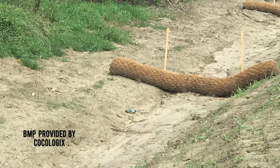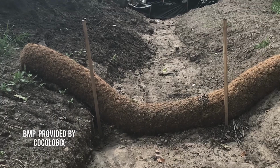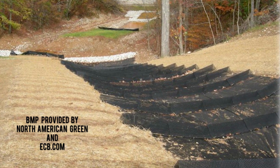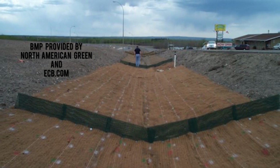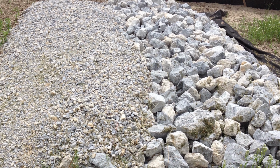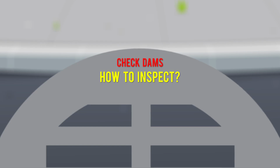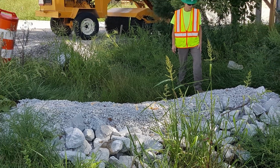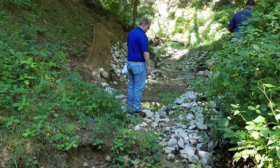How to maintain. If significant erosion occurs between dams, install an erosion-resistant liner in that portion of the channel. Remove accumulated sediment when it reaches 1/2 of the height of the dam to maintain channel capacity. Allow drainage through the dam and prevent large flow from displacing sediment. Add riprap and aggregate as needed to maintain design height and cross-section of the dams. How to inspect. Inspectors should check for erosion between dams, sediment accumulation, as well as appropriate riprap and aggregate amounts.